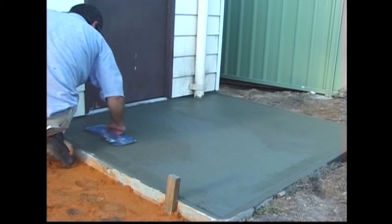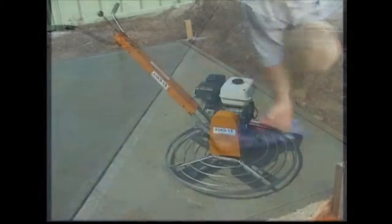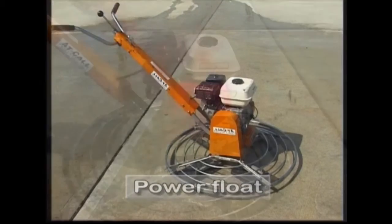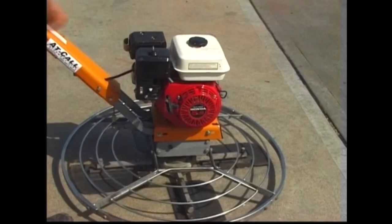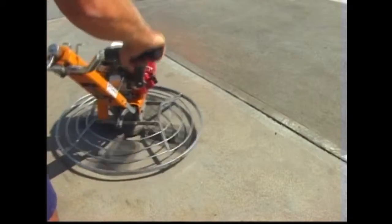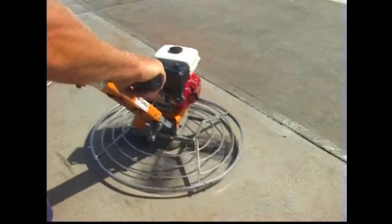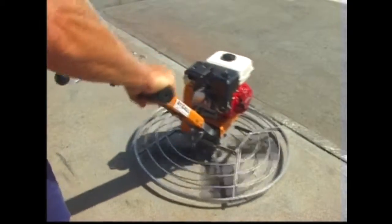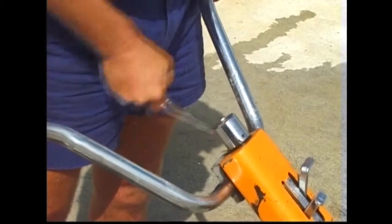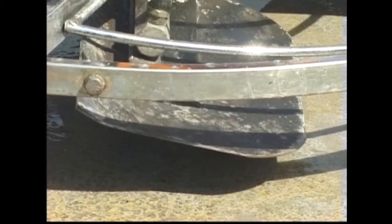Concrete surfaces are finished by floating. Small jobs are conveniently done by hand. Larger expanses of concrete can be mechanically finished with a power float or helicopter. The direction of movement is controlled by raising or lowering the handles. Lifting the handles moves the float to the left and dropping them moves it to the right. As the concrete becomes hard, the pitch of the blades is increased to prevent them digging into the surface.